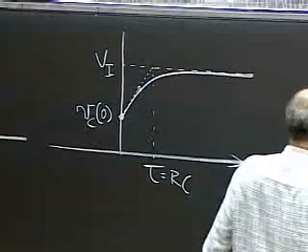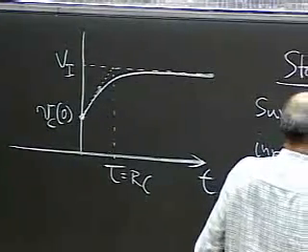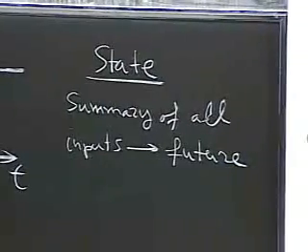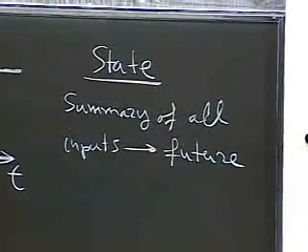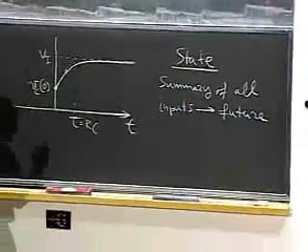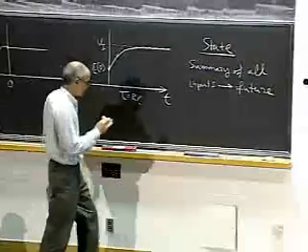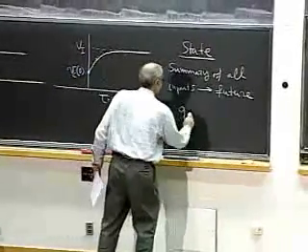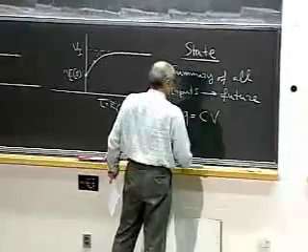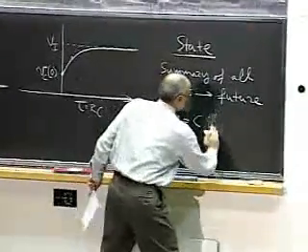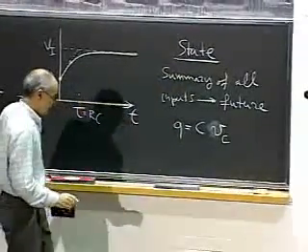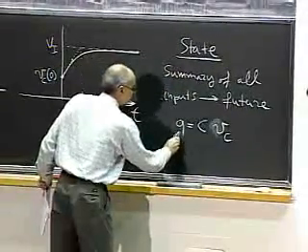So it predicts the future. Now, what is the state variable on the capacitor? What is actually stored on the capacitor? You can say, well, what is stored is voltage. The real physical quantity that is stored is the charge, Q, which is, for linear capacitors, related to the voltage. Oh, let me actually write it correctly, V sub C, like this. So the real state variable is this.